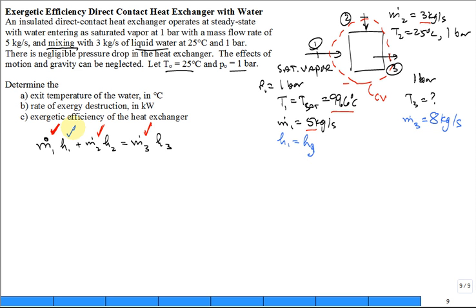How about h2? Oh, it's subcooled liquid water, 25 degrees C. You can get it. I think we can. How would we get it? h2 is equal to hf at 25 degrees C. That's a great approximation. True? So we can get h2. The only thing unknown in this energy balance equation is h3. So I actually calculate h3, and now I know the pressure. So I compare h3 with hf and hg, and I see it's in between.